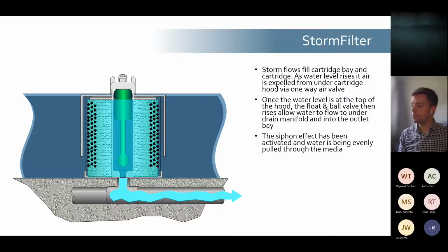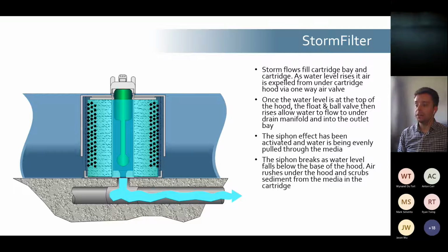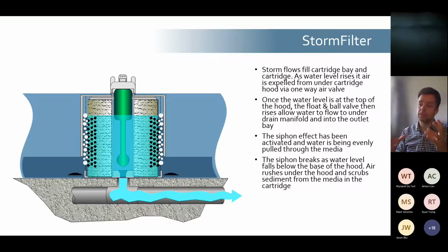And at that point, the siphon effect has been activated, pulling water evenly through the very large media area. Once the water starts draining down, the siphon then breaks. At the point the siphon breaks, air bubbles come up, and they physically agitate the media.